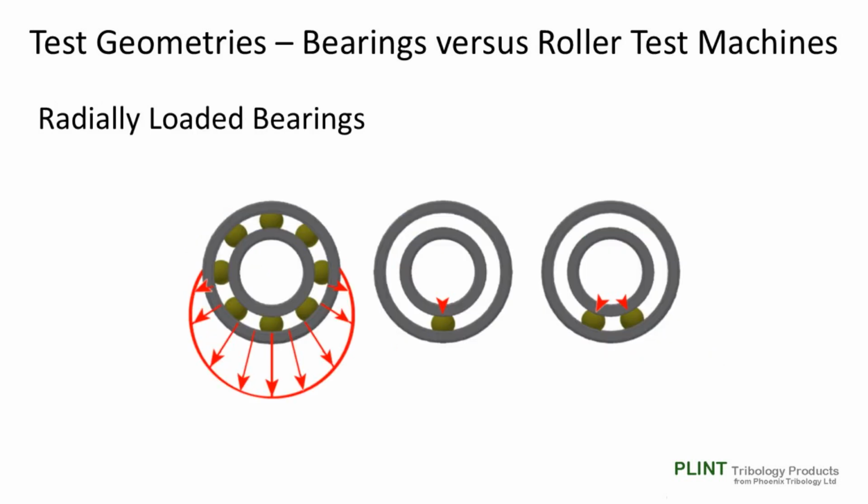When it comes to rolling element bearings, everything becomes much more difficult, and in the case of axially loaded angular contact bearings, spectacularly so. As a result of this, and going back to the early days of Palmgren and Lundberg, the tendency has been not to define bearing test conditions and resulting bearing life in terms of contact pressure and number of fatigue cycles, but to define the test conditions as applied load on the bearing and rotational speed, with the L10 life simply the number of hours run at that load and speed until failure occurs.